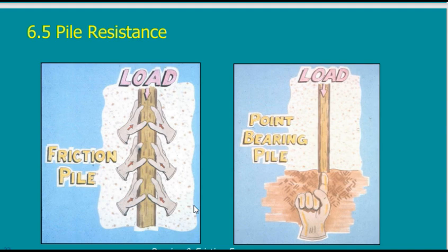If I have a pile and I studied the friction and I found that the friction is 50 ton. Yani, according to friction, the pile can carry 50 ton. And according to end bearing, the pile can carry 40 tons. If I have a tension load, what is the maximum that the pile can carry? It is the 50 of the friction. But the 40 of the end bearing will be zero because they will not work in tension case. So this is the main difference.